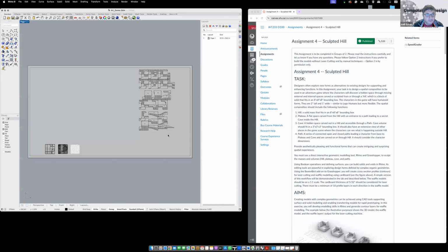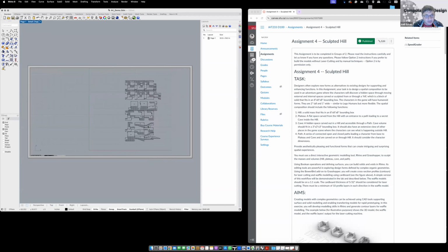Once you create one, it gives you this view. And this is a viewport. Essentially, if you double click on it, it takes you to model view that you can zoom in and zoom out. If you click outside of it, it freezes it, nothing happens. That's your view. And this is the layout. Remember, I already defined my margins.